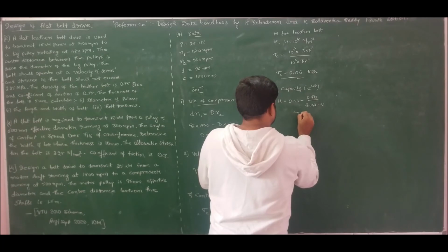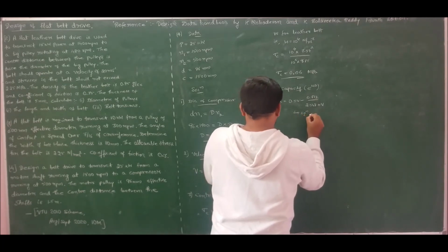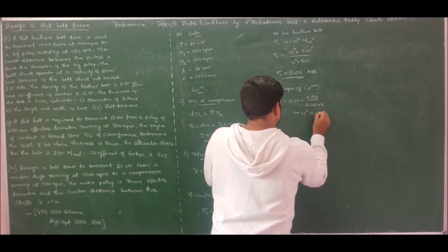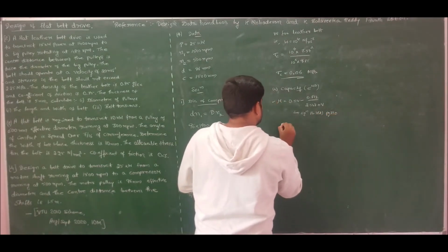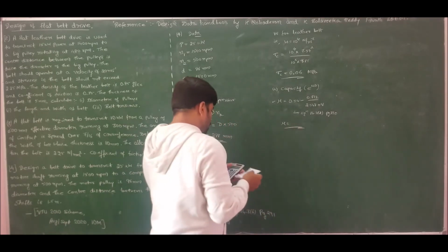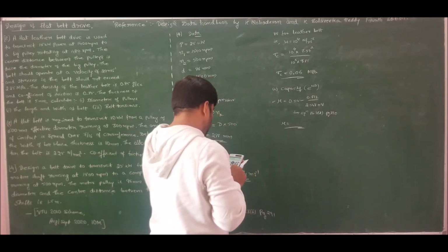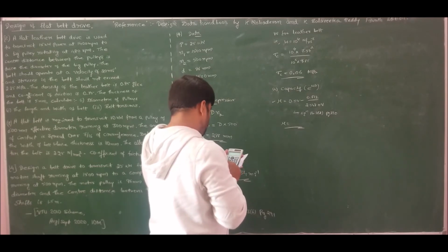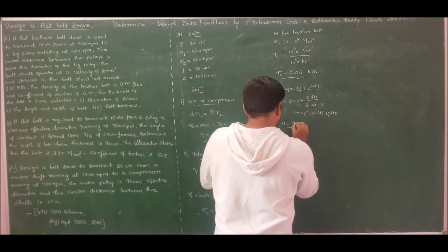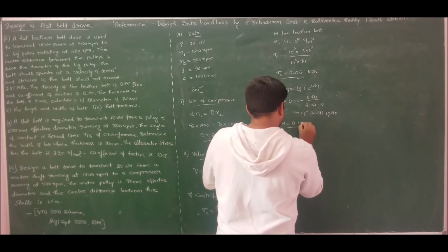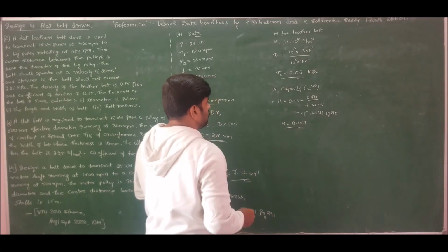So this is equation 14.3d, page number 290. So if I substitute and solve, I'll get the coefficient of friction as 0.54 minus 0.712 divided by 2.542 plus velocity is 7.54, which is nothing but 0.469. 0.469 is the coefficient of friction.